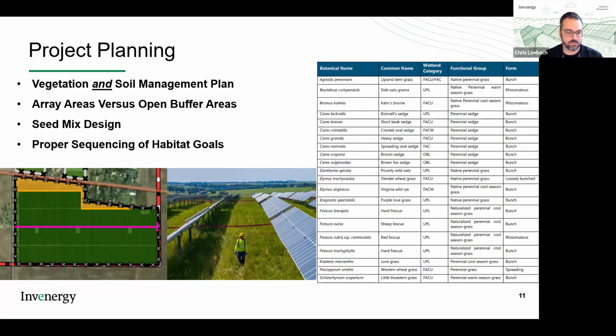So they help stabilize the soils, outcompete the weeds, hold the fort down while the natives continue to fill in. And what's really important is ensuring you have an appropriate seeding rate. So we're using these naturalized species at a seeding rate that's more aligned with a restoration project as opposed to trying to establish turf grass. So we're getting these species out on our site, but there's still plenty of matrix space to allow those natives to find their place and fill in over time.